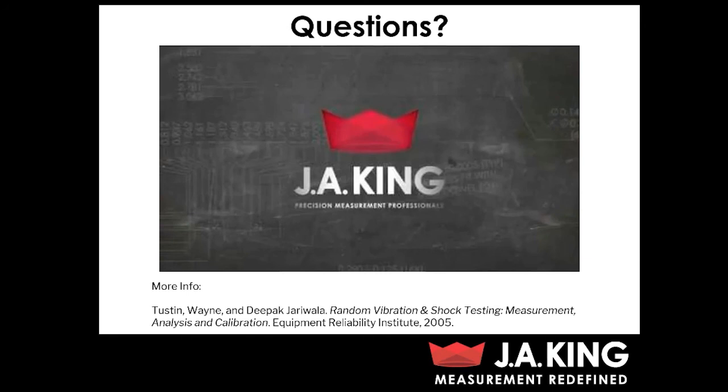And how can you accelerate a test? Okay, so there's a few different ways to accelerate testing. We can choose our temperatures to help us accelerate testing, so we can increase the high end and decrease the low end a bit. You can also increase your irradiance. So when I was going through designing a test, we chose an irradiance of 1,050 watts per meter squared. This is going to be the noonday irradiance at the equator. So this is a worst case scenario, so that can help you accelerate testing.